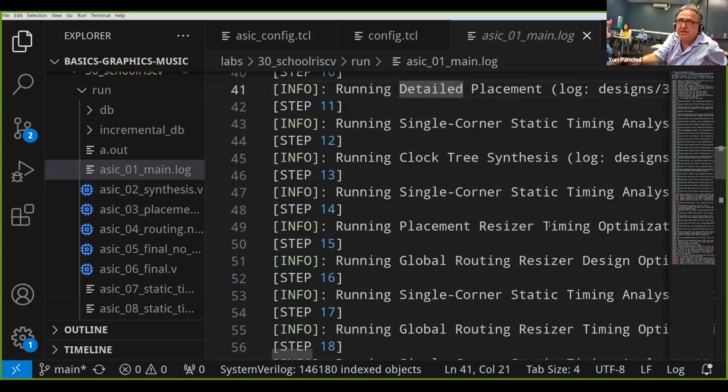So we have this clock tree synthesis, which guarantees that your clock signal splits into several signals, and each splits into several signals. We finally get a clock tree where the signal goes to each single element of memory, which is a D flip-flop, at the same time.